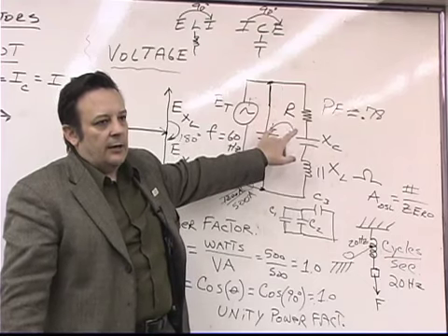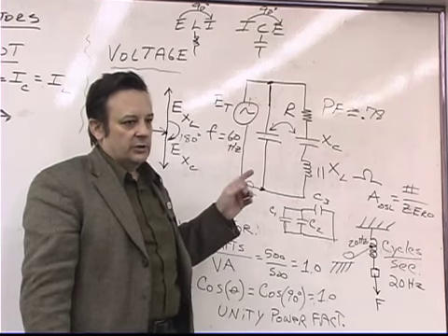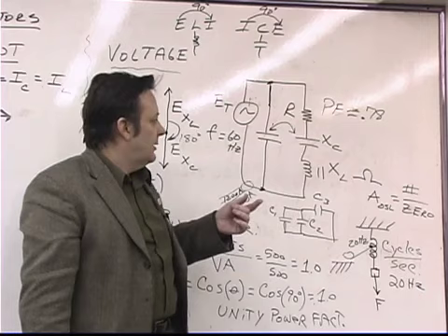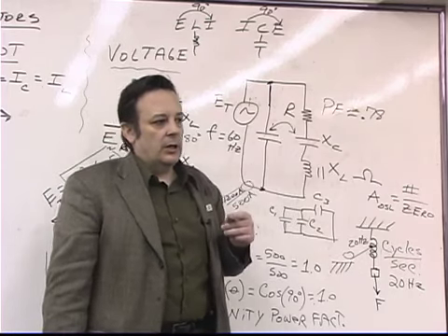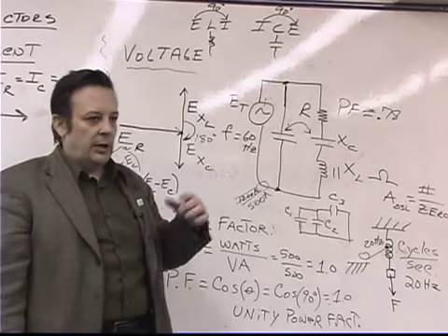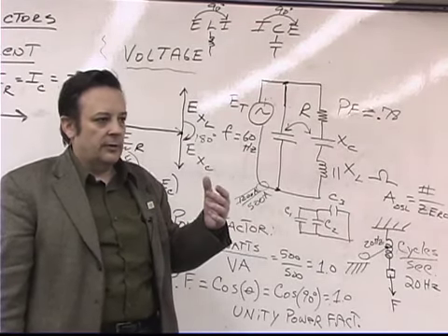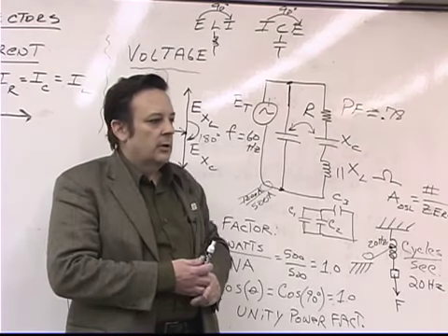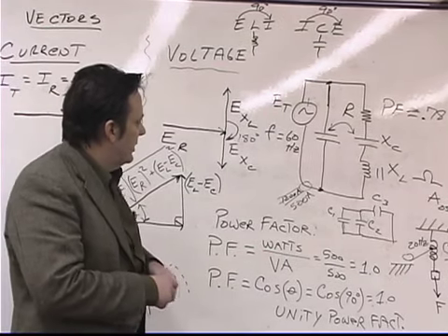So that same philosophy that applies to a mechanical system also applies to an electrical system. So if you get into a resonant condition in an electrical system and you don't intend to be there, then you can actually do more harm than good. So that's why you have to be very, very careful before you put in power factor correction to make sure that you haven't created a series or parallel resonant circuit. Okay? So we'll talk about that some more as we continue our studies.